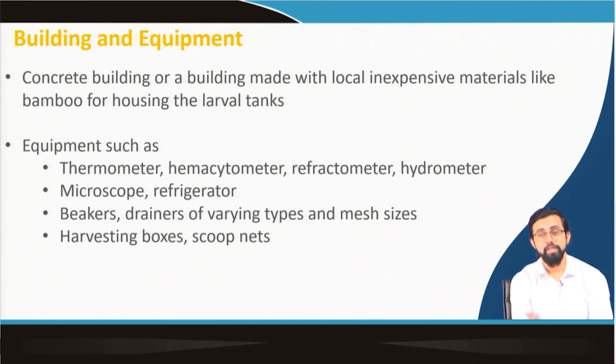Even if the temperature outside is a little bit less, the temperature inside will be at least 4 to 5 degrees Celsius higher than outside, because of the greenhouse effect, right? This low wavelength, high wavelength sunlight phenomenon. Because of that, it sometimes makes sense to design poly houses for this kind of hatchery design.